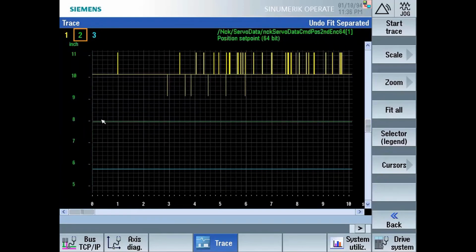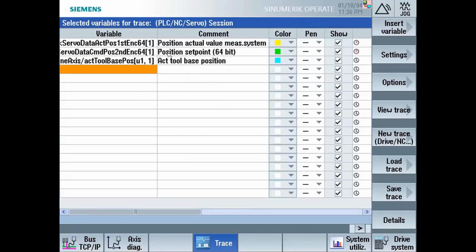My position set point with the uncompensated one is still at a little bit less than 8, 40 thou, and we still get my jitter coming off of the motor encoder actually moving. Well, not jitter, just dithering. Jitter's a timing thing. So I used the wrong word. Sorry. So we go back. I'm not grayed out anymore because I now have data.